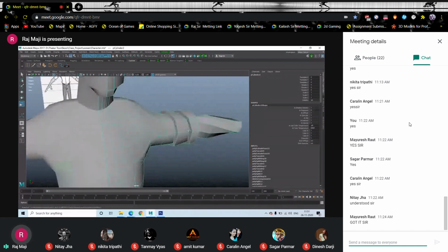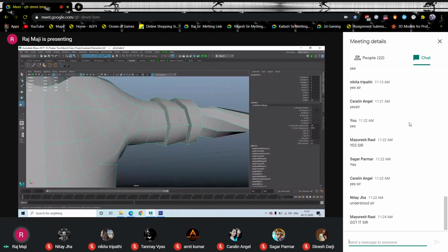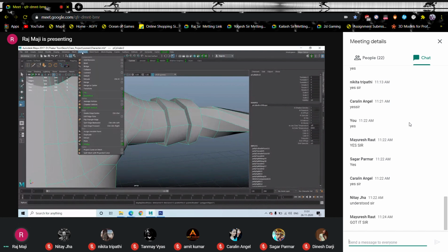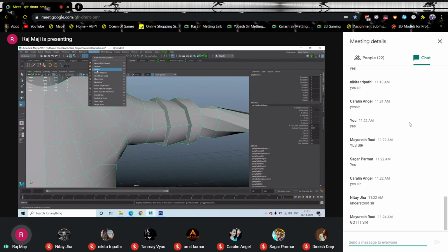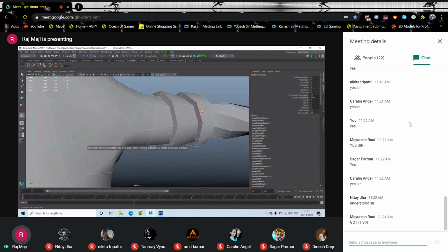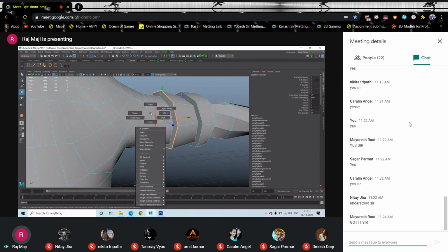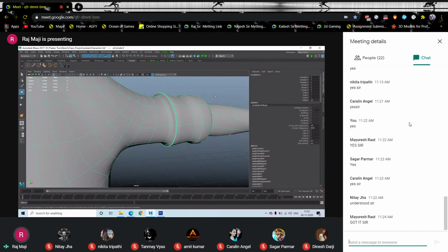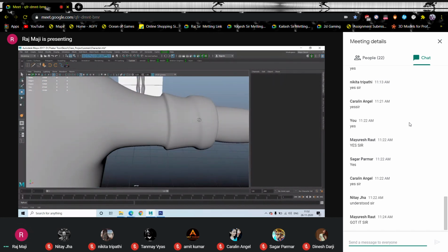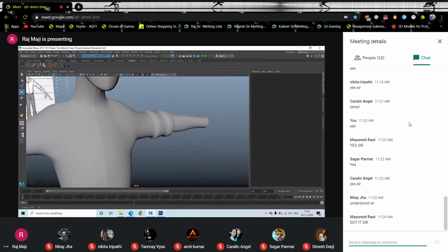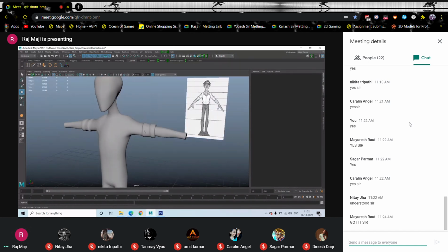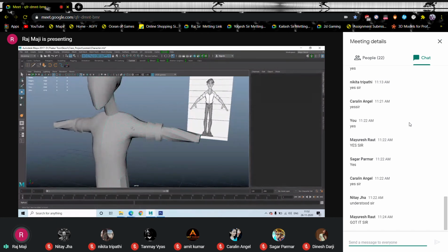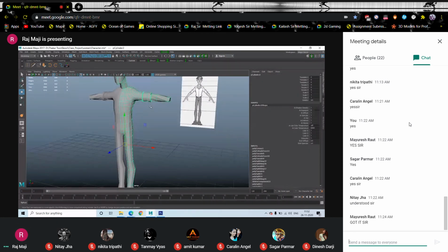Okay. Now another thing we do, because when we are pressing 3, this is also blended. We don't want that. So what can be done? Go to mesh tool, go to crease tool. Okay. Selecting the entire edge loop you want to crease and middle mouse drag. So let's check what's happening. Pressing 3, now it is creased. Right? Okay.